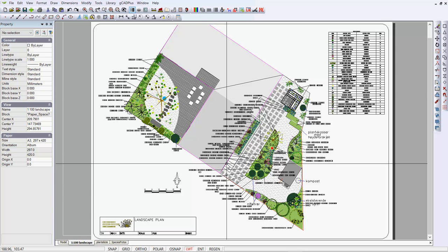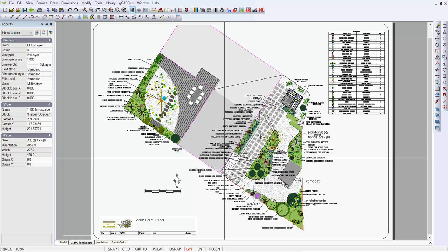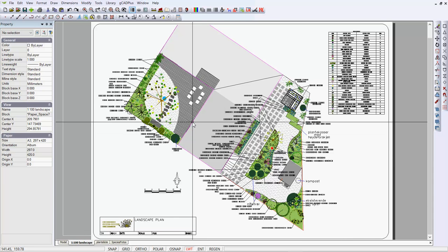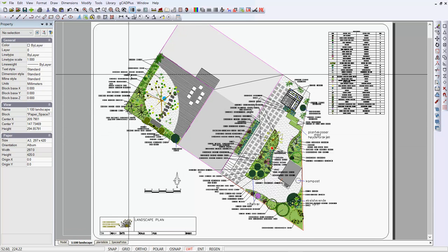None of the PDF writers that we've been able to find will print transparency, so you do need to check your drawing for the use of transparency before you set a print out to one of these high resolution PDF writers, where you can set the resolution to, say, as high as 1200 dots per inch if that's what you want. Let's show you one little trick that can help.